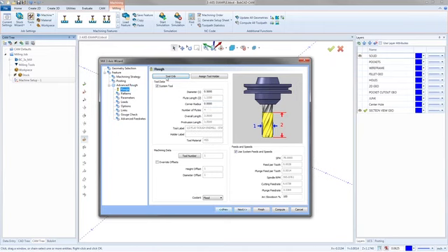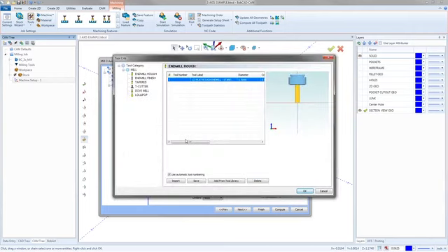Just so you guys know, if you haven't seen it yet, to know whether you've picked a tool or whether BobCAD picked the tool, go up to the tool crib, go to this bar right here and bring it all the way to the right. And you'll see right here, it'll either say auto or picked from library. Picked from library means you picked it. Auto means BobCAD picked it. And yeah, that's pretty much it.